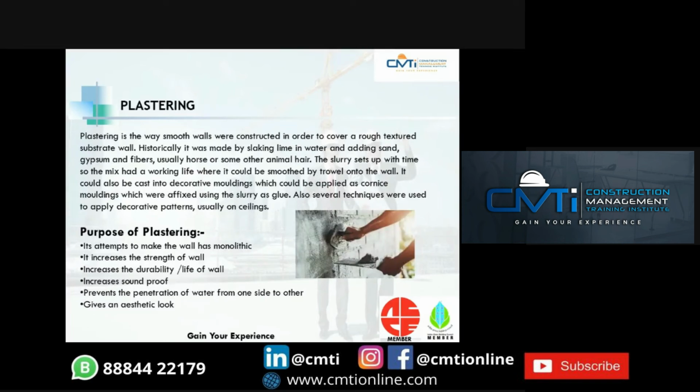Next is plastering. Plastering is the way smooth walls were constructed in order to cover a rough textured substrate wall. Historically, it was made by slaking lime in water and adding sand, gypsum, and fibers, usually horse or some other animal hair. The slurry sets up with time, so the mix had a working life where it could be smoothed by trowel into the wall. It could also be cast into decorative moldings, which could be applied as cornice moldings, which were affixed using the slurry as glue. Also, several techniques were used to apply decorative patterns, usually on ceilings.